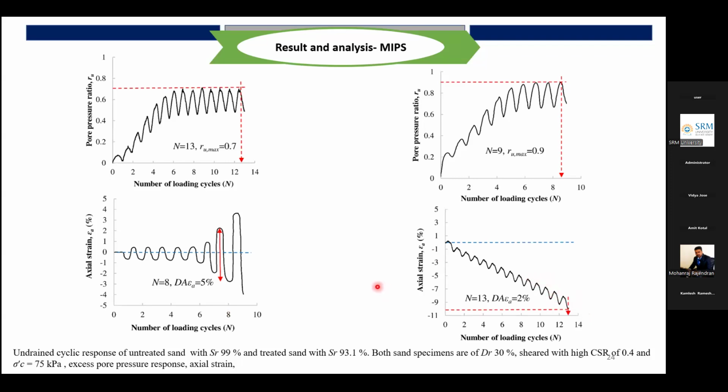So one is where you treated the soil, you are trying to reduce this strain criteria, thereby your soil is not liquefiable. So both the stress criteria and the strain criteria are checked in the treated soil. So treated, meaning only unsaturated soil, is having very good liquefaction resistance.